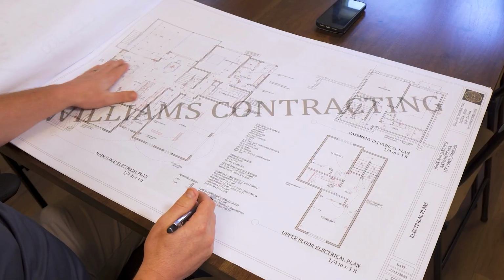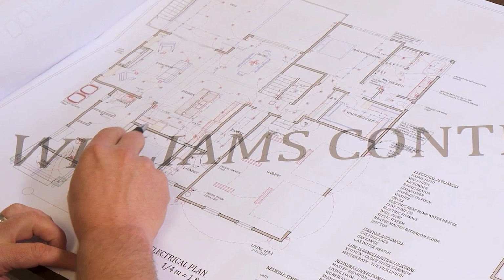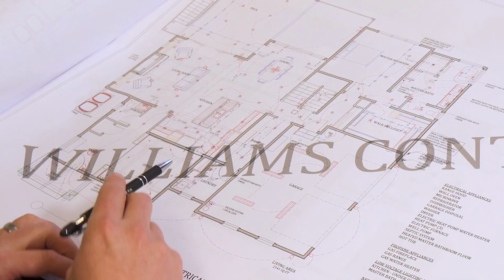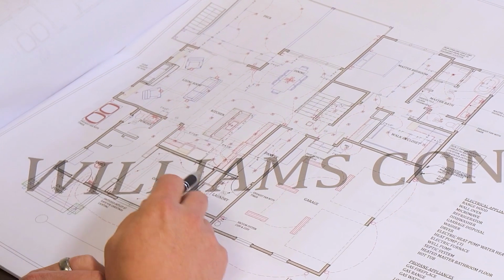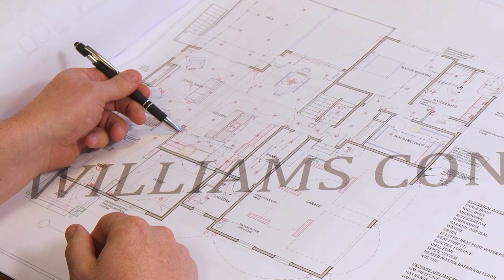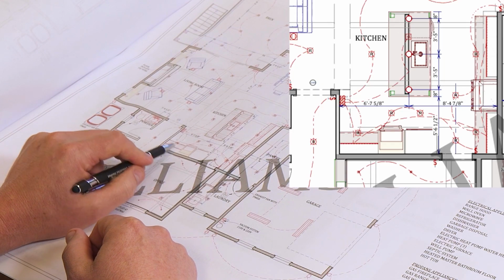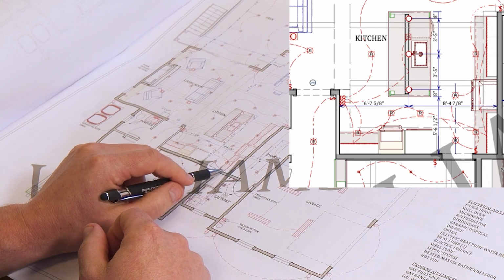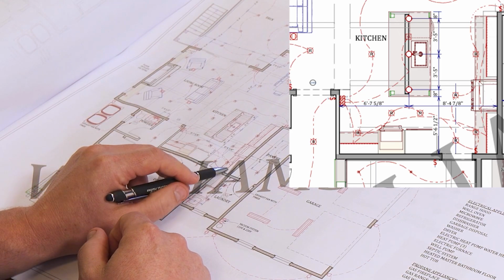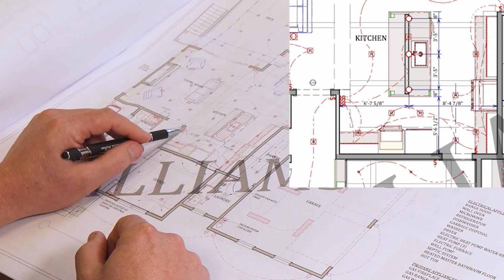First off, we've got our standard lighting plan. So you can see each of these symbols is a recessed can light, and we're showing a switching setup. So sometimes, like in this kitchen, you've got a lot going on, so it's important to pay attention to what light is switched to where. We have a switch bank here. This switch is coming to this red line, which is an under cabinet light. This under cabinet light is connected to these under cabinet lights is here. All of these, as you can see, the line ends here, so it means there's a single switch here.